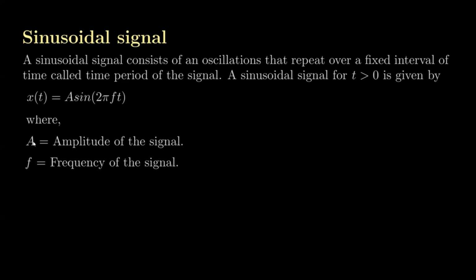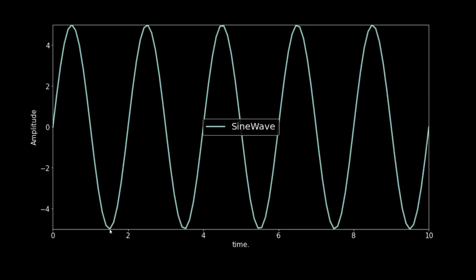When time equals 1, the signal's amplitude is 1. When time equals 2, the amplitude is 2. And when time equals 4, the amplitude is 4. The magnitude of the signal is equal to the value of time, and that is why we say the ramp signal increases uniformly. This is the simplest form of a continuously increasing signal.